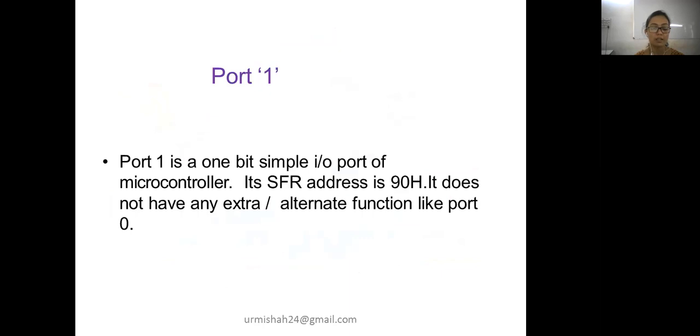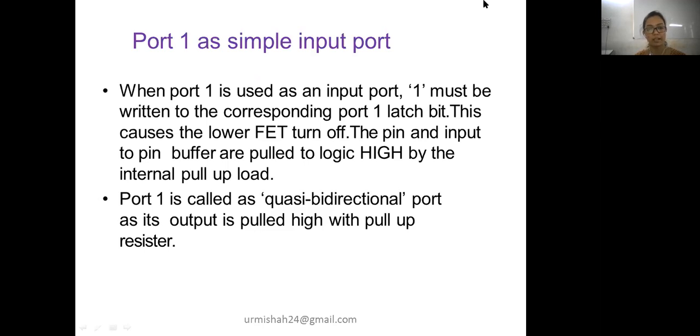Now port 1 is an 8-bit simple I/O port of the microcontroller. Its SFR address is 90H. The SFR address previously for port 0 was 80H, but for port 1 it is 90H. And in port 1 we don't have any extra or alternate functioning like port 0. In port 0 the extra functioning was the read modify write option, but here in port 1 we don't have such a facility. So this is regarding port 1 as a simple input output port.